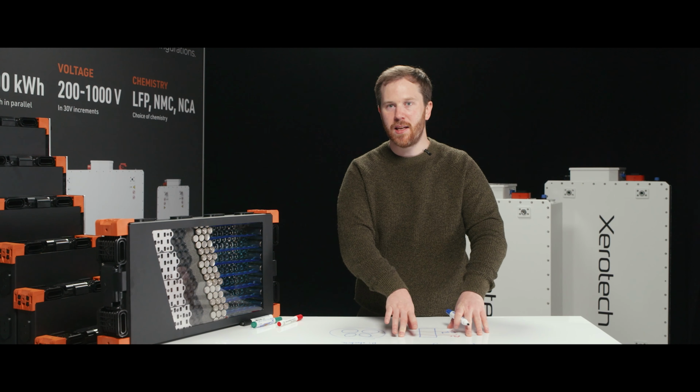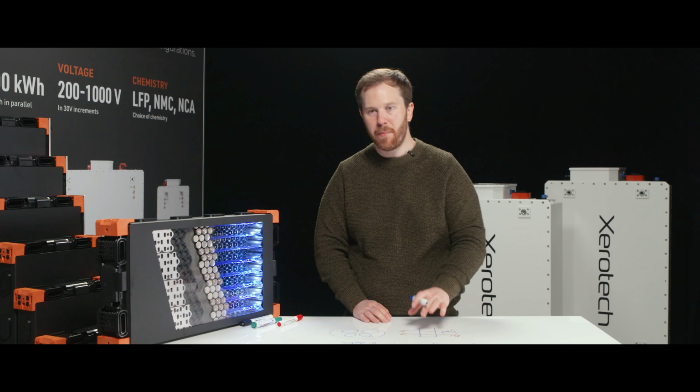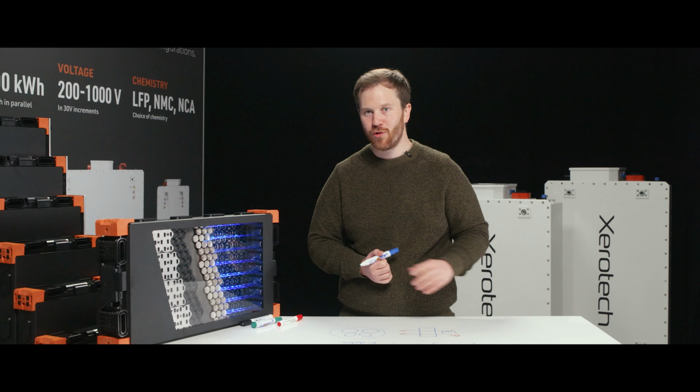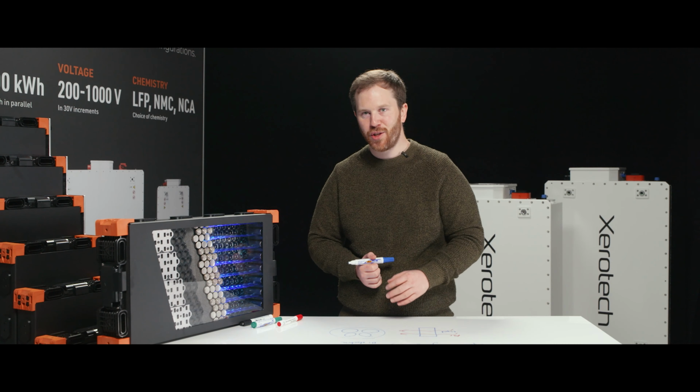So that's directly cooling the battery cells. It can be an effective way, especially with direct immersion cooling or direct liquid cooling, but the challenges there are more practical, of heavier solutions. Your dielectrics have lower thermal performance in some cases, and obviously leakages of the whole battery pack system because you have many more leak points in place.